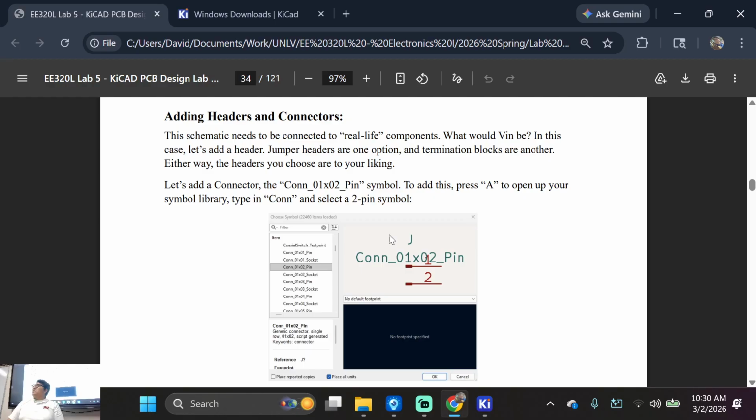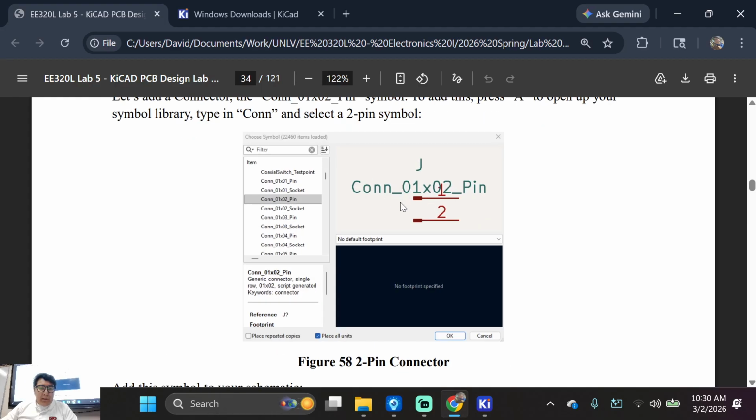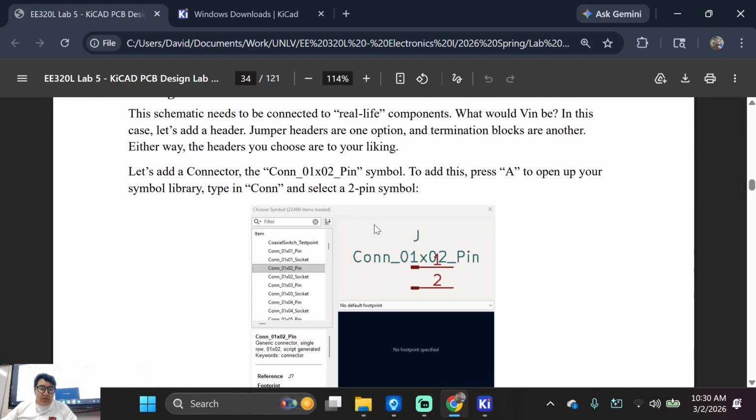So how do I probe into my PCB? You're going to need headers. You're going to need some copper. You need some actual components. So I purchased special components. There's these little green headers that you guys probably saw around. Let's see. I purchased some nice ones here, okay? So KiCAD doesn't really know what you're talking about other than just symbols, okay? You need to assign those footprints.